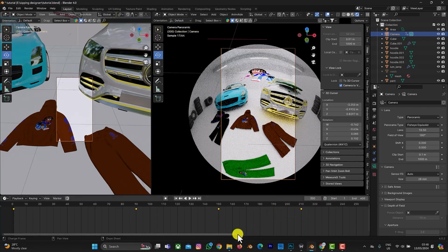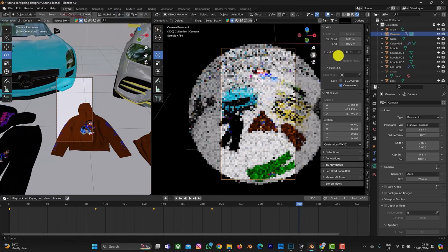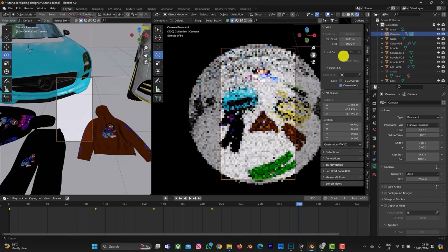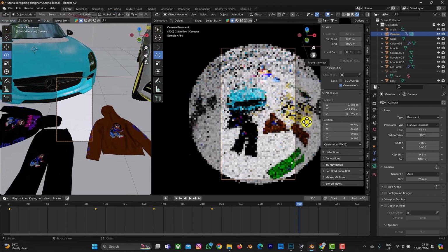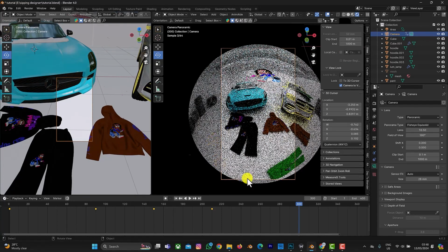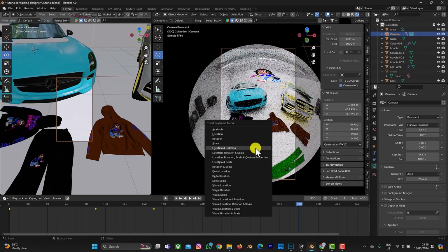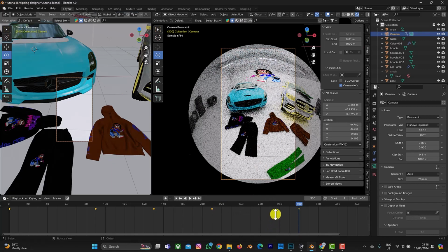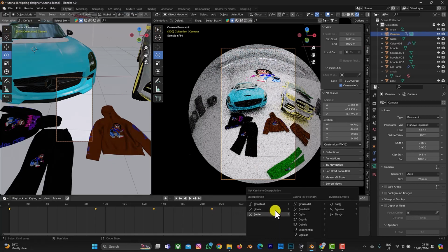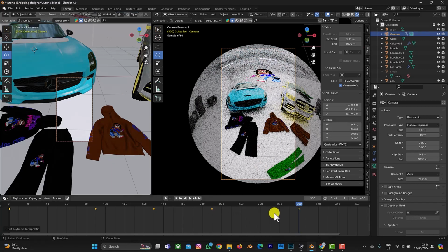Then you can drag here to see the next move. So next thing, you just drag from right to left. You can make it 3 seconds. I think it's slow enough to give a little information about the design. Then the next thing you do is to click on I to insert keyframe. Then you go here, select Bezier. All this I'm doing manually.